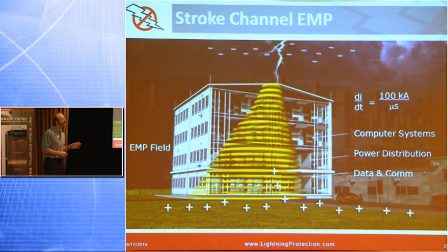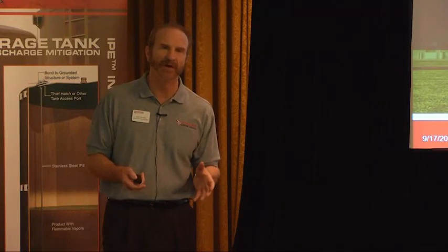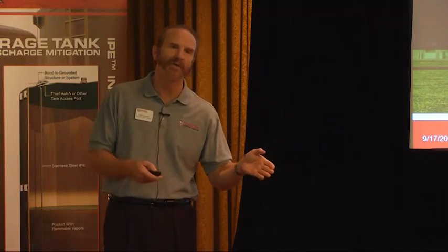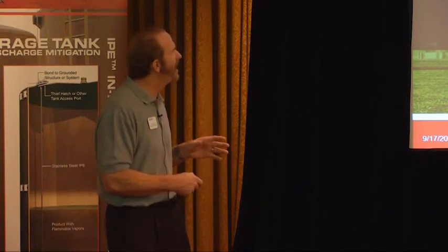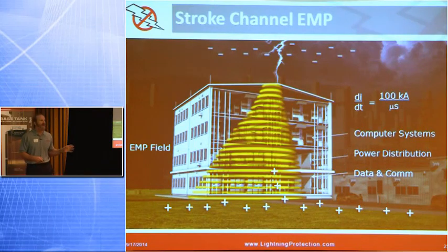Now, most of our lightning strikes probably won't do that. We don't have a bell curve here, but in general, lightning is not consistent by its normal discharge currents. It can be as low as 2,000 amps to well over 400,000 amps. Average around 30,000 amps. So if we have to be 100 kA, 5 strikes out of 100 are 100 kA and greater. So only 5% of our strikes get to 100,000 amps or greater. They're pretty rare. But if you had a high lightning current strike with a fast rise time, you run that equation, you can develop a pretty significant EMP.